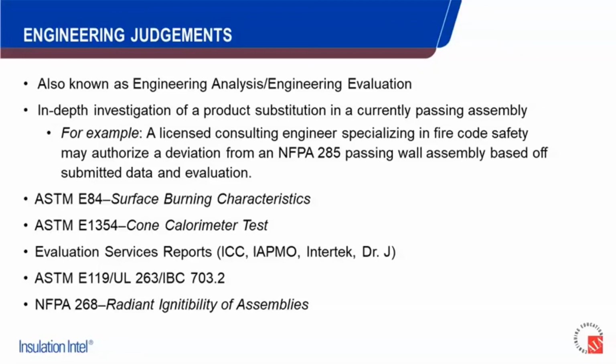And that really boils down to the cone calorimeter test. That's the test that's measuring the embodied fuel, if you will, inside that material. So you can see the various benchmarks they often use in making that decision, but that tends to be the big one. It's all based on fire performance. They're not concerned about whether it's airtight, or whether it's going to maintain my WRB, my drainage plane. They're specifically looking at fire performance and combustibility in relation to whatever material we're considering exchanging it for.